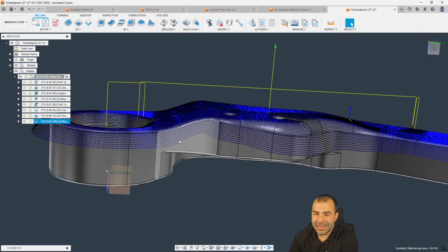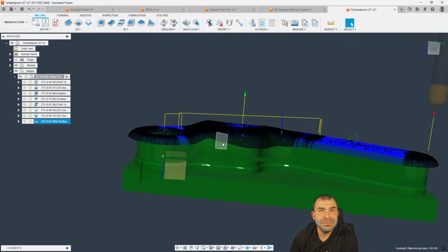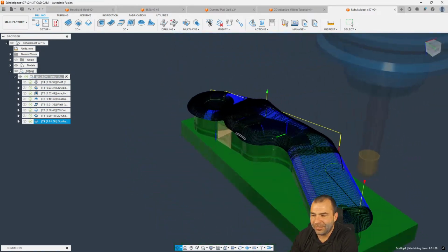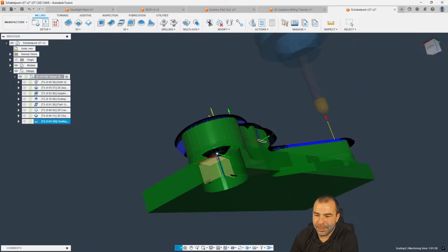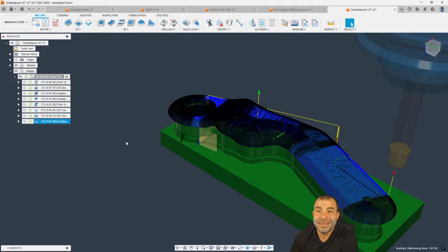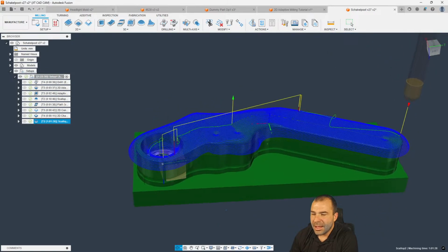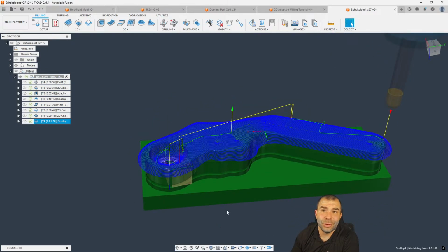But by adding in 0.1 millimeters, I guess, according to the way this is set up, notice how much I can clean up this toolpath fully all the way around that part. So by being able to set that up and put that in there, let's get the toolpath points turned off. Again, I've been able to adjust and manipulate what path I got, right? So I got a path, then I narrow down where I want that path using avoid touch surfaces.